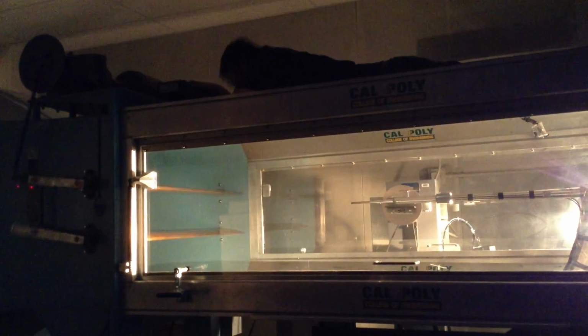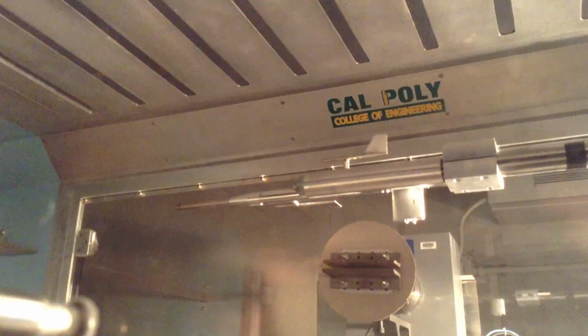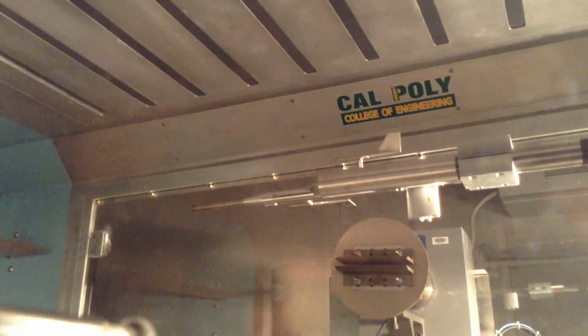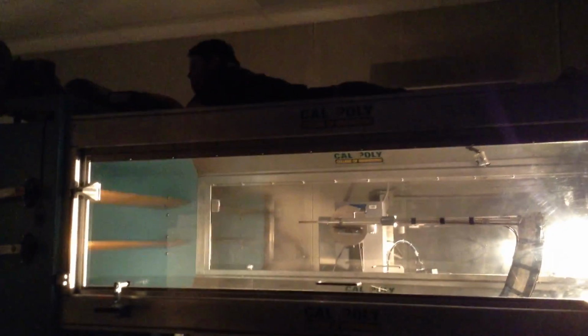We would like to be able to measure the vane position and frequency and measure the gust magnitude and the frequency of the gust, and be able to compare that against known values to see if the system's acting accordingly. If the data does not match up with the calibrated measurements, then we know there's a problem in the system and it must be corrected.